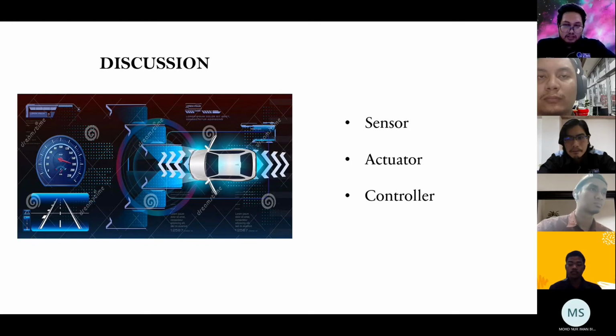Okay, the next one is the controller. The DSP technology is a combination of microprocessor and microcontroller technology. Real-time operation, compact and small-scale hardware, and fast processing speed are constantly required, most particularly in driving applications. The Harvard type design allowed the DSP to perform parallel processing by maintaining two independent bus structures, the program and data bus, and the specific instruction set allowing the processor to execute at maximum speed. Okay, next slide.